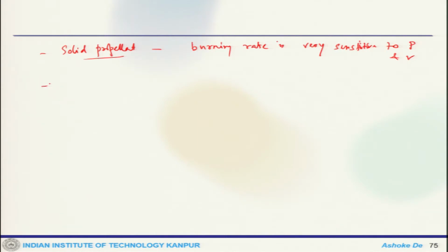Then you have energy release and propellant velocity or the pressure pattern that interact to produce sustained oscillation also. So, there could be oscillation from other sources, and this comes from that energy release, coupled with the propellant velocity and or the pressure pattern that develops inside the chamber.